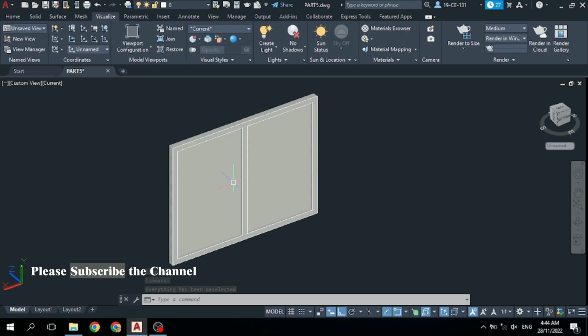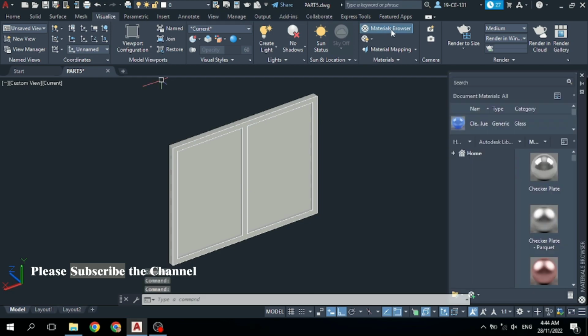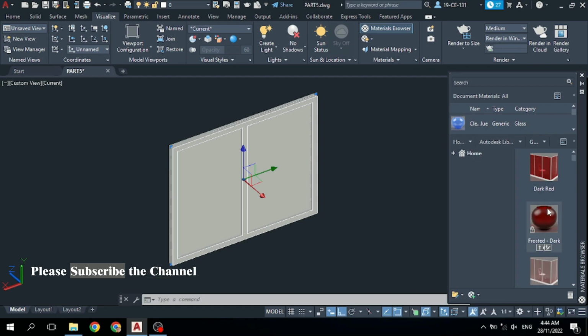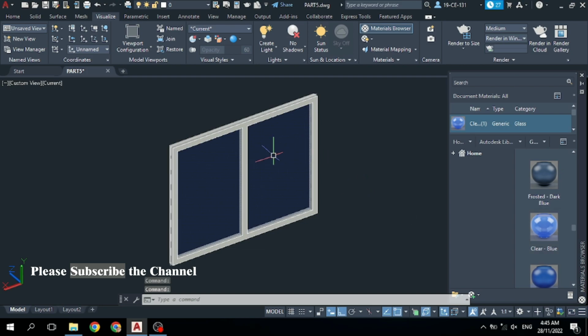So after that I would like to add the material for this window. So for that click on this visualize and then click on this add material browser. Here you can see, and you know that this is a glass. So now I would like to add the glass material. Come here and select this glass, and here different materials and different options are available. Select any, you can select any of them. So now I would like to select this one. You can see this blue one, so simply click on it. Now you can see it is added.